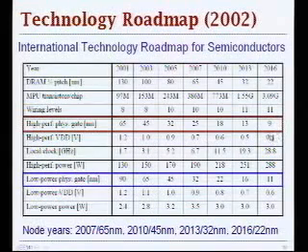This is going to end up in 0.4 volts for high performance and about 0.6 volts for low power. And the main reason for this is basically leakage power. So basically, if you keep scaling your VDD and VT very aggressively, then the problem becomes your leakage power.